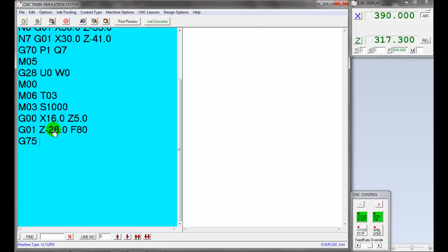Let's enter the parameters of the grooving cycle. R1 is the retraction in mm. X diameter 11 mm is the groove depth. Z-30 mm is the groove end position. P 100 microns is the depth of cut for each pass. Pecking Q 1000 microns is the stepping distance after completion of every pecking. F 40 mm per minute is the feed rate.